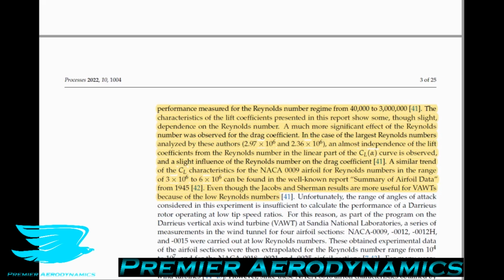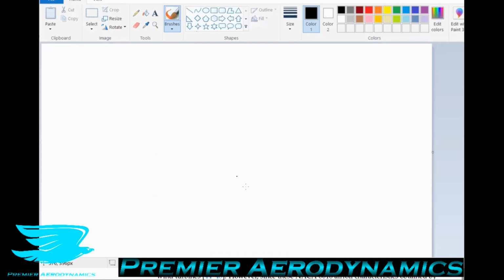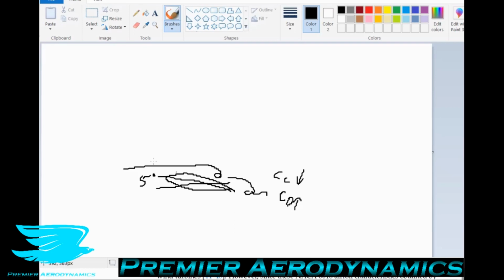So why is this? Well, the reason is because if we have an airfoil, it doesn't really matter what angle of attack it is, but there are some differences to some extent. So let's say we have a low angle of attack to begin with. That's pretty high, but let's say it's about 5 degrees. If you're just listening to this, you can see the video on Spotify and on YouTube. So let's say it's 5 degrees. The flow goes over it. If we have a very low Reynolds number, it means that the flow is going to separate potentially, and we're going to get quite a large wake. That's going to result in the lift coefficient dropping and the drag coefficient increasing. If we have a high Reynolds number, then the flow will be able to stay attached longer, and we'll get a much smaller wake. So the lift coefficient will now start to increase more, and the drag coefficient will reduce because that wake is smaller. That's what the Reynolds number does.